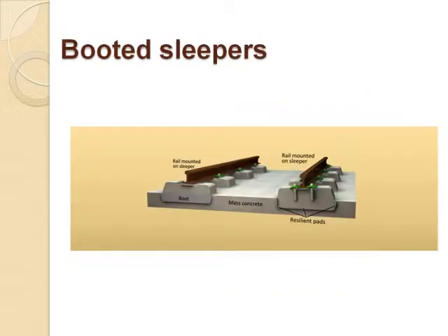Booted sleepers is that the rail is mounted on a twin block concrete sleeper, which is wrapped with resilient boots recessed into a concrete slab. The sleeper block sits on an elastomeric pad and is surrounded by a boot. Therefore, the elasticity is provided by the rail pad and the resilient pad beneath the rail. This system is used mainly in tunnel constructions.